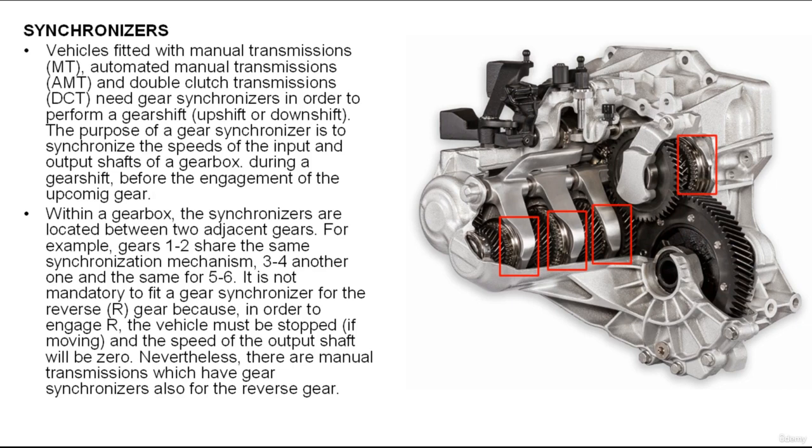In some transmissions, a synchronizer can have another important job. When spur teeth are cut into the outer sleeve of the synchronizer, the sleeve can act as a reverse gear and assist in producing the correct direction of rotation for reverse operation.